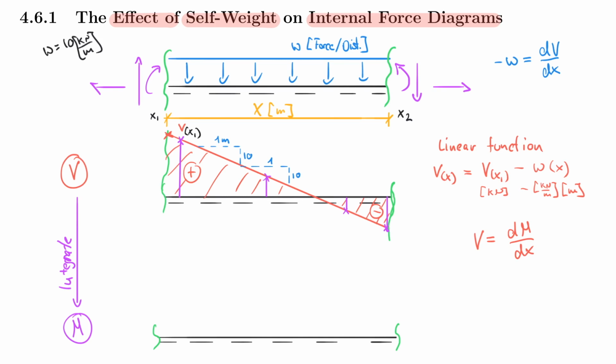And of course, the one thing I never need to explain to my students is that here I have a zero value. So here V of x is equal to 0, or the shear force at that location is equal to 0. Therefore, everybody understands that when you go to the primitive, or the parent function as I sometimes call it, I have a local maximum or minimum here. And that is something we can often agree on in the classroom.